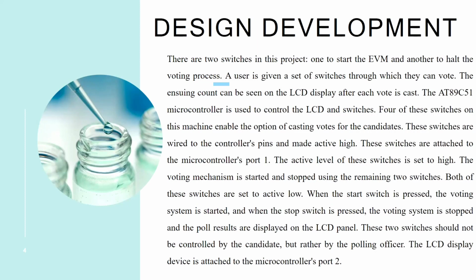The AT89C51 microcontroller is used in this hardware. It is a 4-port 8-bit microcontroller. Each port has an 8-bit width. It has a flash memory of 4K bytes, 128 bytes of RAM, and two 16-bit timers or counters.